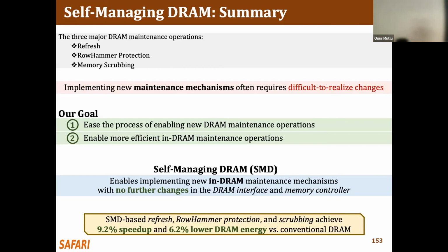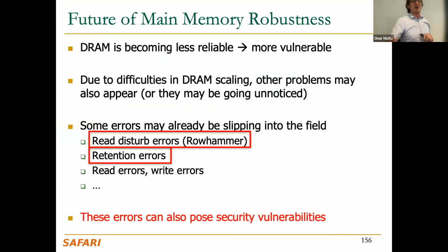Meaning, if you actually have a RowHammer solution that's perfectly secure, you can actually cause denial of service by attacking a row, because internally there will be a lot of refreshes going on. But that's true for this interface also, and that needs to be examined. So denial of service, I think you need to be careful about. But at least you're not doing data corruption. Denial of service, hopefully, is a little bit easier to deal with. In the end, I think it'll be degradation of service and not complete denial also. Yeah. Okay.